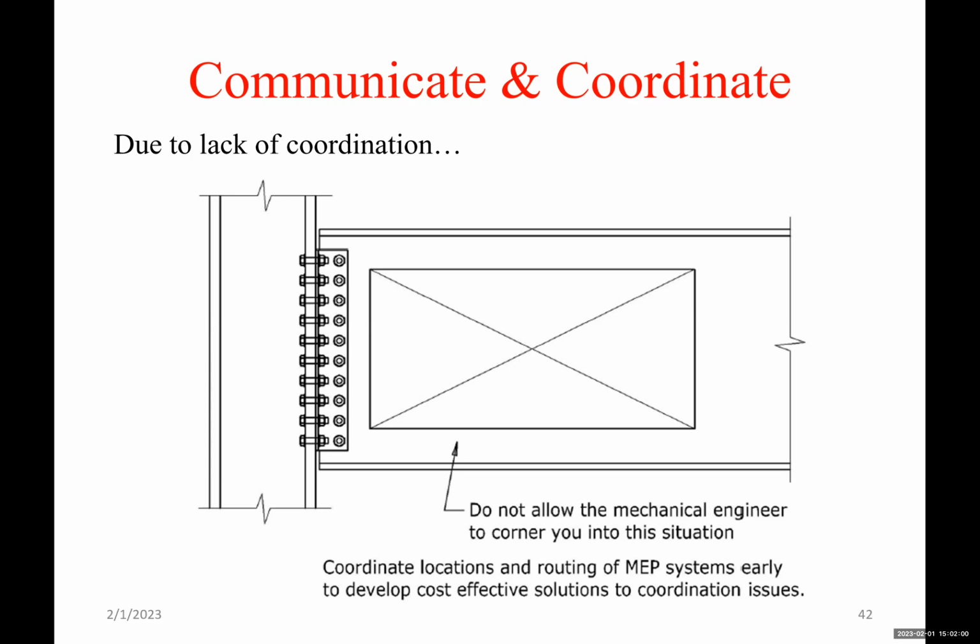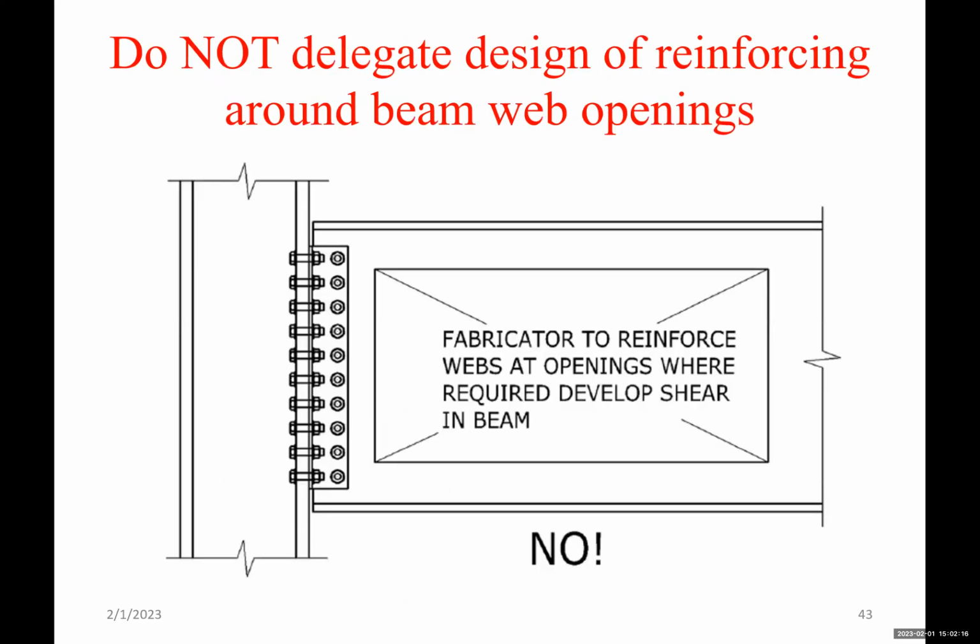And where the high shear force is, which is at the end of the beam. So what do you do now? This is due to lack of coordination. So coordinate, okay, coordinate. So you avoid something like this. Do not delegate design of reinforcing around beam web openings.